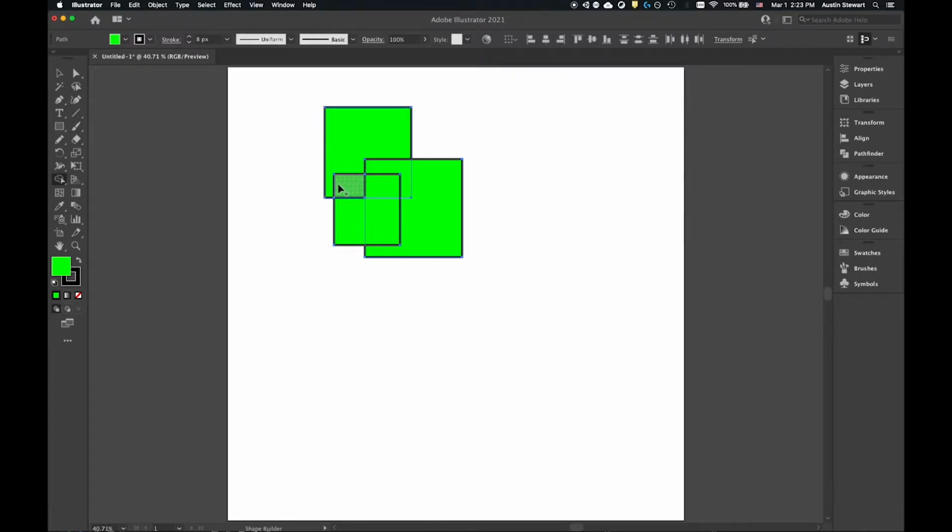So if I click, it adds a new shape. If I hold down Option and click, it will subtract that shape. So it will get rid of that shape and leave the resulting shapes with this hole in it. Then the other way that it works is if you click and drag. Whatever objects you drag over will be joined together as one. So if I want to join these 3 things here together, I just click and drag, and you'll see now there's this red outline. And I let go, and now this is one big shape.